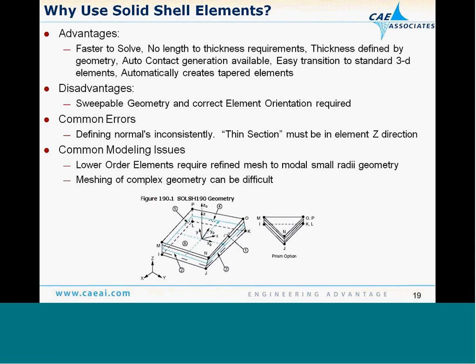The different elements is that you have to be a little careful when you define them. You want to make sure that you mesh with the thin surface operation, or if you're defining them manually, you create a consistent z direction, since the thin direction where ANSYS will decouple the translational response and moment response is only defined correctly if the z element coordinate system is normal to my shell elements.